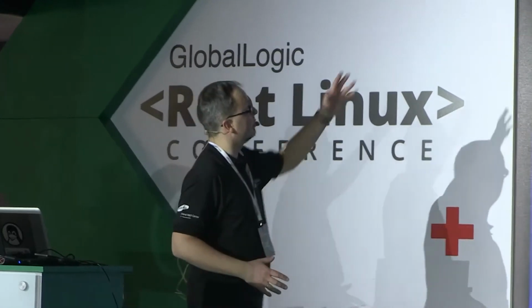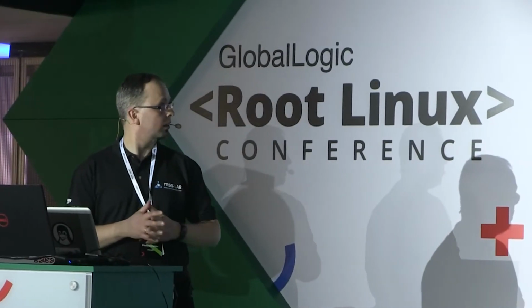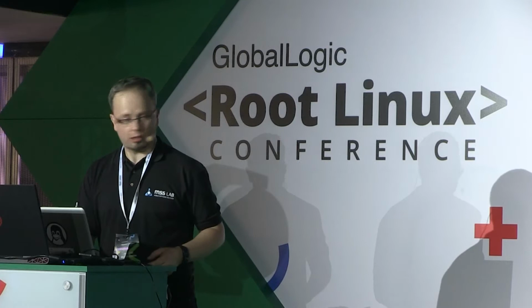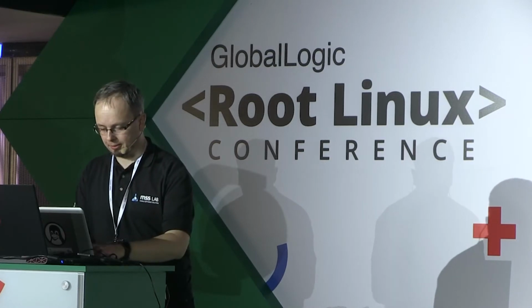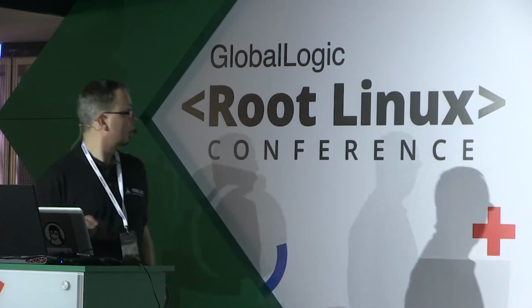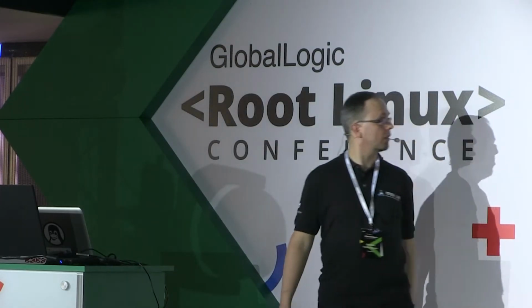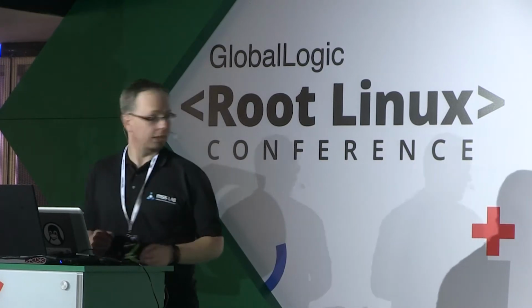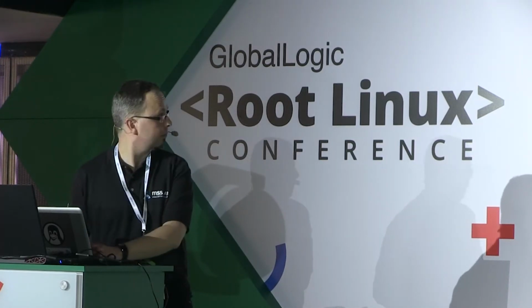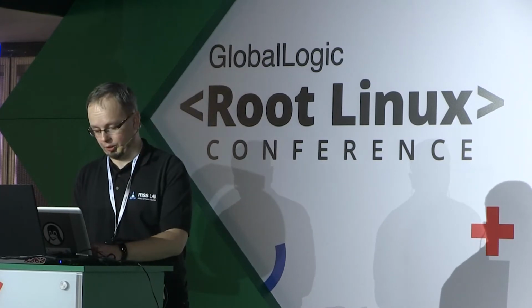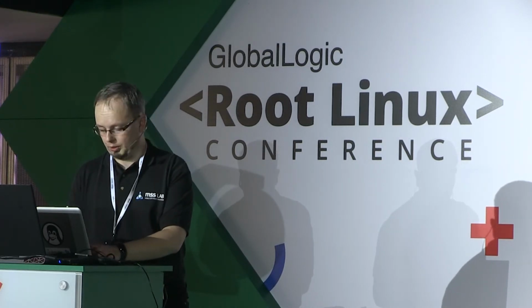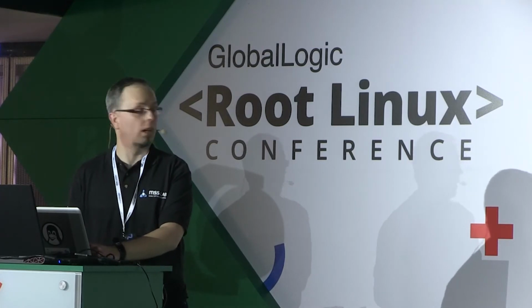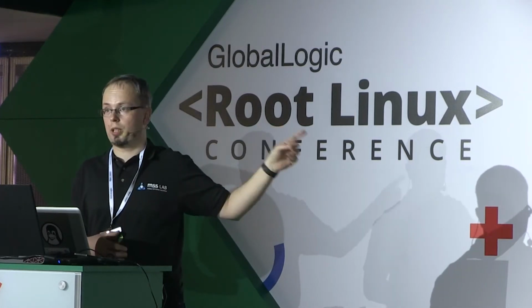There exists a gt tool, a gadget tool, which is a command line tool which uses libusbgx. Let me show you this command in action on the device. So, with this tool, we can see that we have two gadgets. Let us get rid of them. gt rm -rf g1, gt rm -rf single function. We cannot remove it yet because we have functionfs mounted.